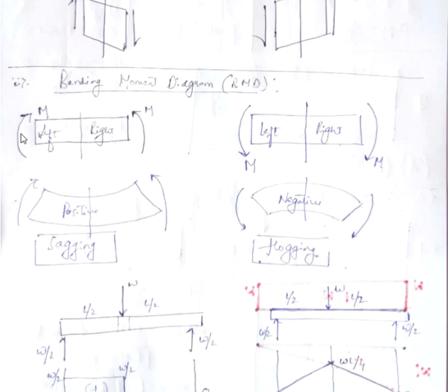Okay, so in this direction, if the bending moment is applied, then it is taken as positive. And if you are coming from left side, again, if the moment is trying to lift the beam in upward direction, then it is taken as positive. In general, if the moments are causing a smiley shape, after bending it looks somewhat like a smiley face. Or you can say if the moment is lifting the beam upward, either you come from right side or from left side, then such a moment is taken as positive, and this shape is called sagging moment.